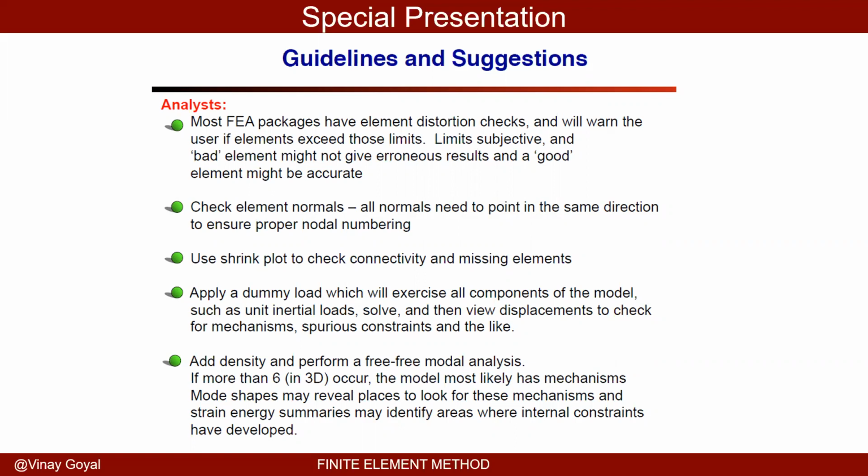Apply a dummy load which will exercise the components of the model, such as inertial loads. Solve, and then view the displacement to check for mechanisms and spurious constraints and the like. Most of the general purpose programs will not abort when you have a rigid body motion, as I have discussed previously. They will not abort because they get a bad name, saying that every time I run this, it bombs. Nobody wants to use software like that. But the issue is, it is your problem. Your boundary conditions are incorrect. So you need to pay attention to that.